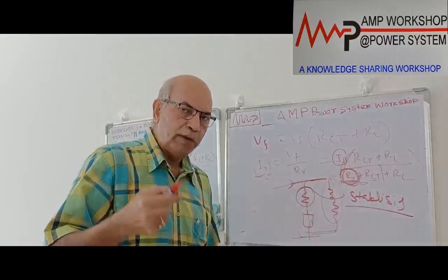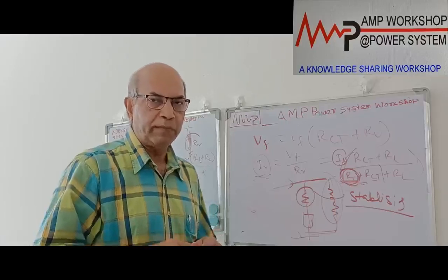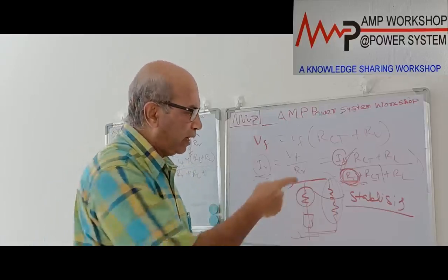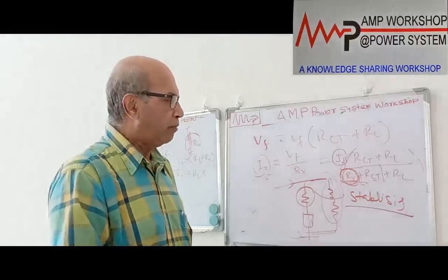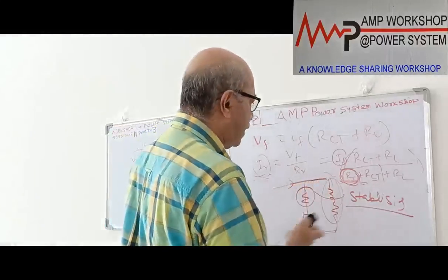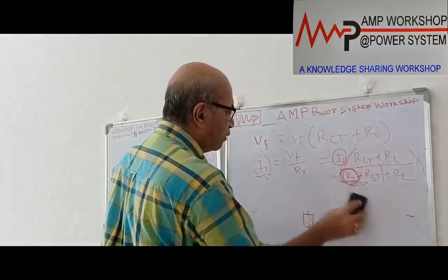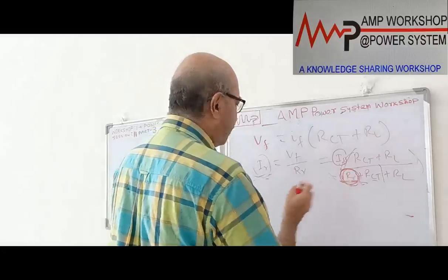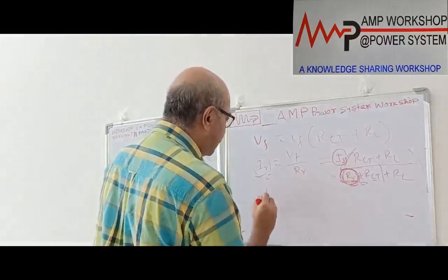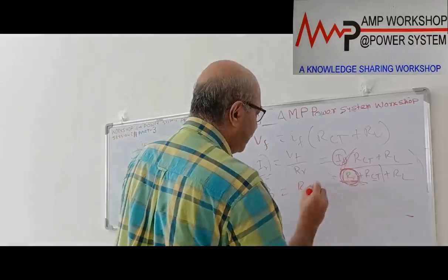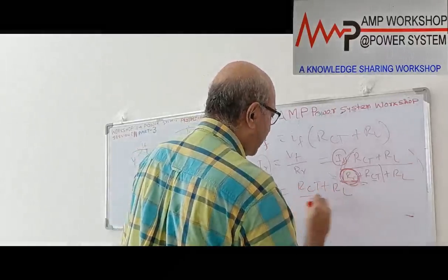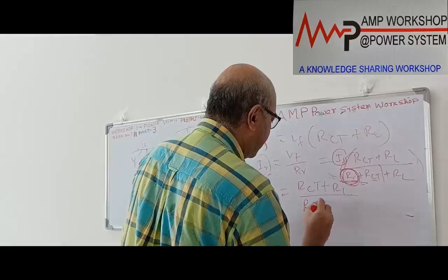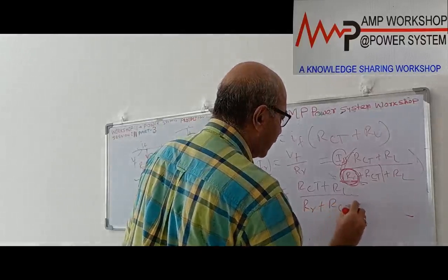Sometimes in the low impedance current differential scheme with bias characteristics, we can include the stabilizing resistance, and we can calculate the stabilizing resistance value from here. For the bias characteristics, we have already calculated this from the equation. We have seen that B equals IR by IF, so B equals (RCT plus RL) by (RR plus RCT plus RL).